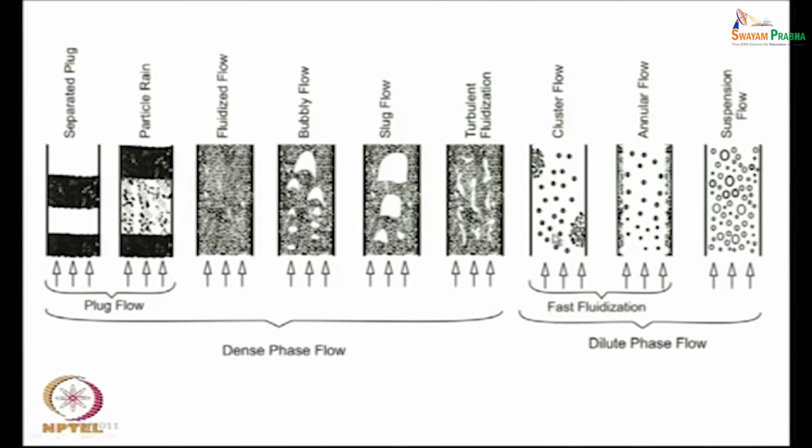So, then we have a transition from the dilute phase to the dense phase. Now, we define two types of choking velocities. One is the accumulated choking, the other is the classical choking velocity. Accumulated choking velocity we get when the dilute flow becomes non-slugging. For example, from here to here, when the dilute flow becomes non-slugging is called accumulated choking, and this is related to the accumulation of solid at the bottom of the pipeline.